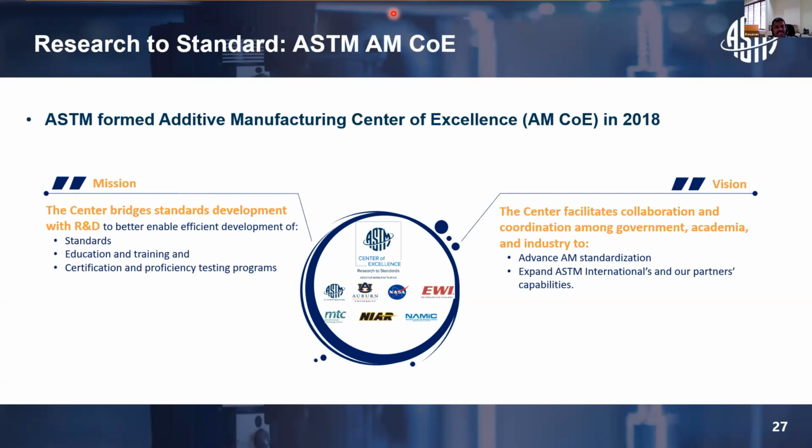When it comes to testing, when it comes to printing, there will be slight variations at two different locations within the printer. For example, if you print a part at the center of the machine, the center of your build plate, and if you have a part at the extreme corner of your build plate, you can expect some difference between these two specimens. So that's the reason why when we do this operation qualification, I talk about IQ, OQ, and PQ.